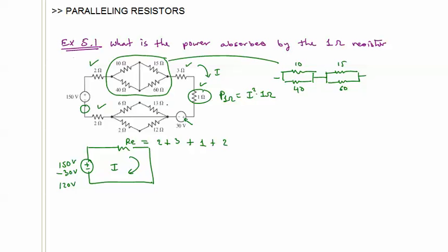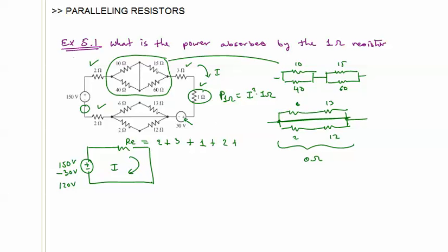And then let's look at this. We see here that actually what we have is 2 resistors in series, that's the 6 and the 13, and 2 more resistors in series, 2 and 12. Those are connected together, but then we have a shorting wire across there. So the whole net effect of this is 0 ohms thanks to this shorting. So we'll say plus 0.